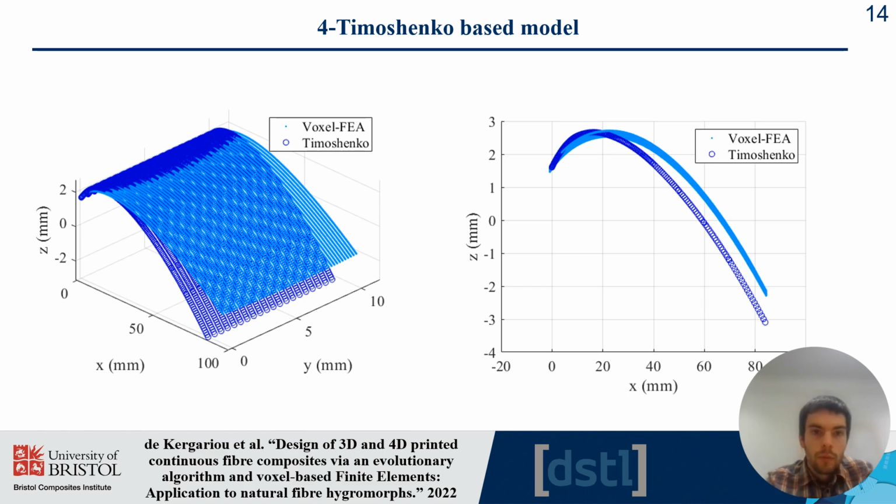You can find all of them in the paper. One that I want to talk about is the corners. Basically, when you print a continuous fiber composite in which you are not capable of cutting the edge, then when you do back and forth, you will leave a little edge on the specimen, and this will have an effect in the actuation, because this material will stiffen the material in the length direction, and therefore our model is capable of accounting for it.